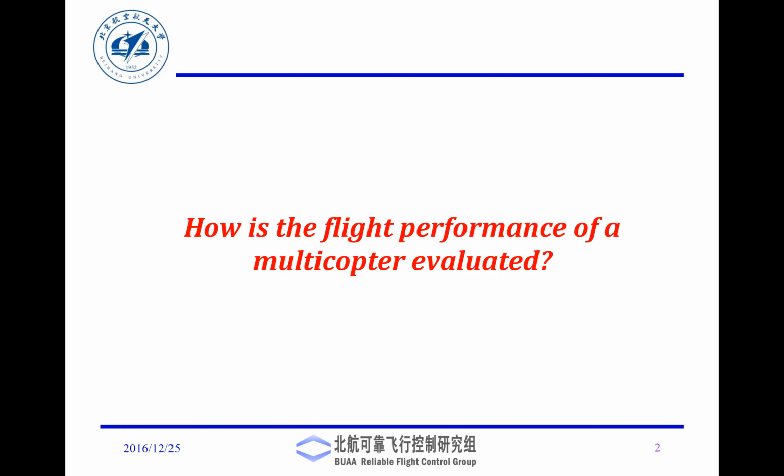This motor does not have sensors. Some motors have sensors, and we need sensors or Hall effect sensors to understand the direction in which the motor is rotating. If you have ESCs that are a little more expensive and sophisticated, they can usually run both sensored DC motors and sensorless DC motors.